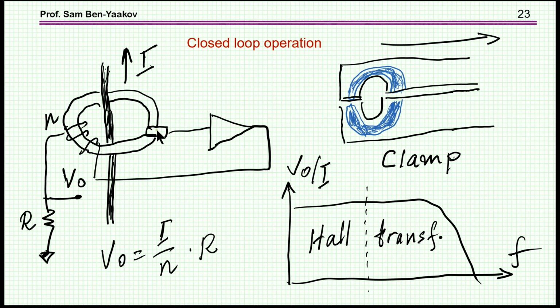That is, we sense the magnetic field variation, or DC, magnify it and push it into a winding of opposite direction of the main current. So the objective here is actually to null the magnetic field within this path. This is a better way to go because then you are not dependent on the non-linearities and gain values. You are just looking for the zero.